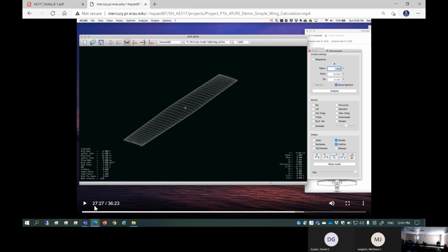Number two is, if your flight condition is more than 0.3 Mach number, you're going to correct all the CP data based on the Prandtl-Glauert correction factor. Okay, so those two kick in. It's coming straight from Aerodynamics 1. I hope you remember those.